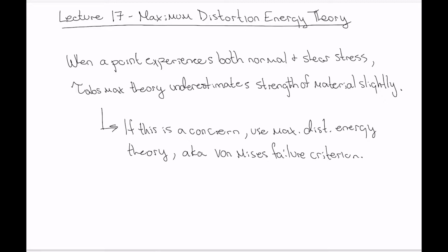You might have played around with finite element analysis of stresses in SolidWorks, for example, and produced what are called the Von Mises stresses. Those are given by the maximum distortion energy theory, and we'll see the equation that's used to calculate those as we look at this theory. The results of this theory predict failure almost perfectly. When it says a material is going to fail, that matches up very closely with experimental reality.